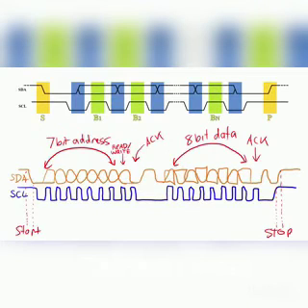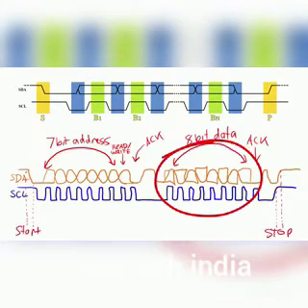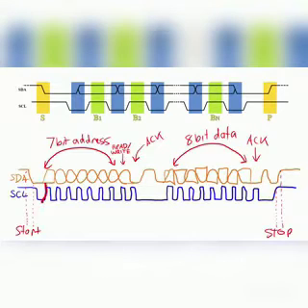So every transaction begins with a start condition. The start condition is when the data line gets pulled low and then the clock line gets pulled low. After the start condition, data is sent. The data that is sent is usually in 8-bit blocks. Each of the 8 bits is sent with a rising and falling edge of the clock. This is called clocking out data. In the case that it's a read transaction, you would be clocking in data. The master still drives the clock, but it doesn't drive the data line.